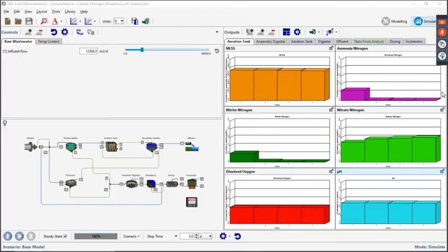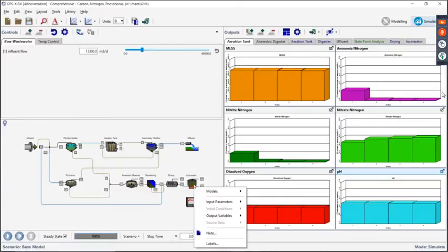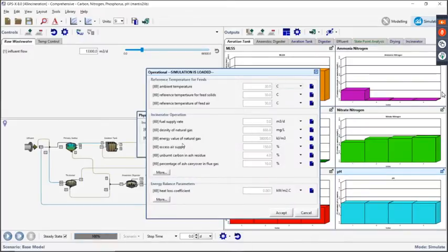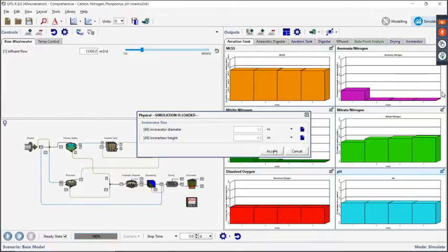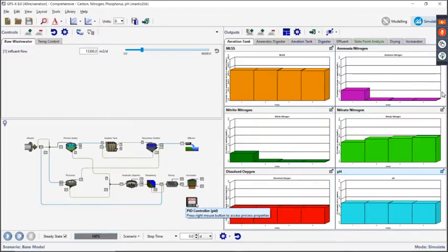Again, we have to know some details about the temperatures and so on, but you'll also see that we need to know things like the fuel supply rate and the air supply rate. There are also some parameters here that you can use to calibrate the performance of the model. In this particular example, we actually have a controller already set up, if you wanted to turn that on. This controller is set up to monitor the fuel flow and make sure that you achieve a specific temperature.